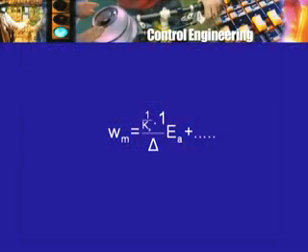So, there is nothing there to write. Do not forget that 1. If you forgot that 1, you would have got 0 there, and probably you will get a 0 for your answer also. So, that is all there is for that expression. 1 by Kb forward path gain multiplied by only 1 that remains from delta divided by delta into Ea, plus the other term which multiplies TL, the load torque.